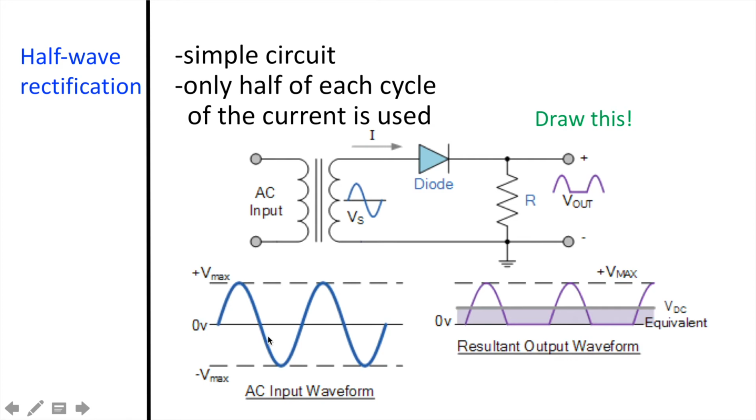During each positive half cycle of the AC sine wave, the diode is forward biased, resulting in current flowing through the diode. During each negative half cycle of the AC sinusoidal input waveform, the diode is reverse biased, and therefore no current flows through the diode or the circuit. So, although we have managed to make the current going to the device flow in only one direction, the current is not constant. We see that there is some time when no power is released. We need to fill in these gaps of no current so that we have a consistent supply of power.